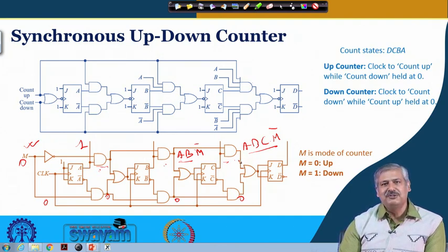So, that issue may come up if you are clocking it too fast, and that needs to be taken care of. Otherwise, it is just only one propagation delay, but for a larger number of bit flip flops associated in the counter design, the fan in could be an issue if we go for multi input AND gates.